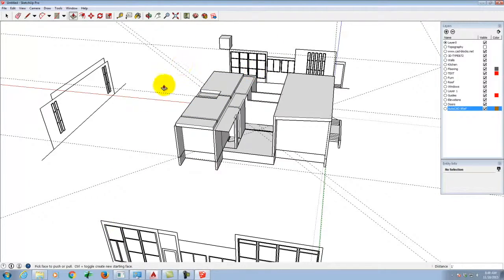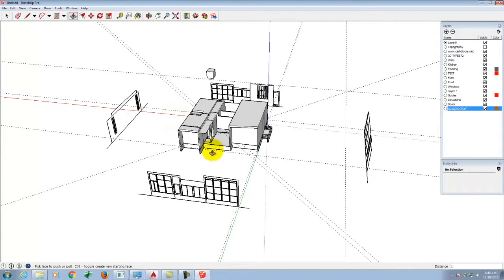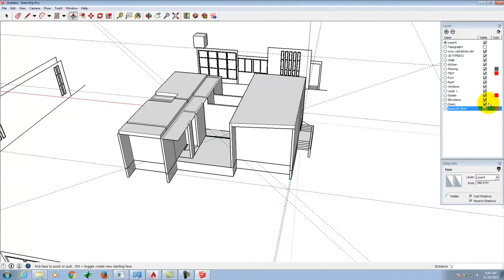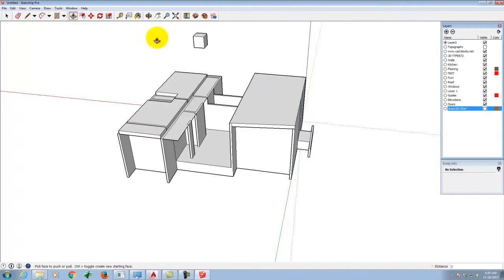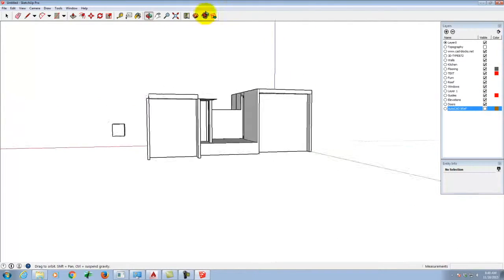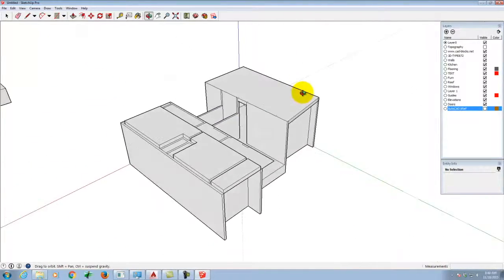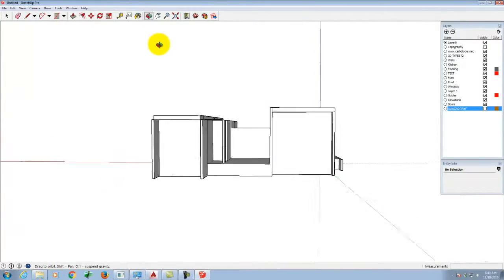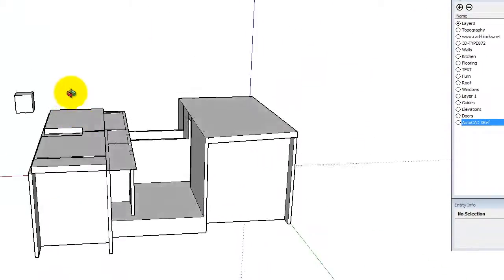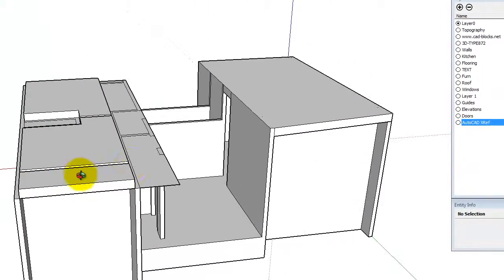Okay? So I'm using each of these elevations as reference for the 3D model. Remembering, of course, that because this is on its own XREF layer, I can turn it off and see just the model that I'm building, of my building. You guys see how that works? Okay? So to me, that's kind of the easiest way to work through this and start to establish what's going on in the building. As you're more and more comfortable with SketchUp, you'll realize that it's really a matter of just extruding, dividing, cutting, right, and continuing.